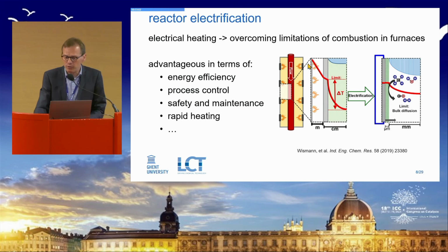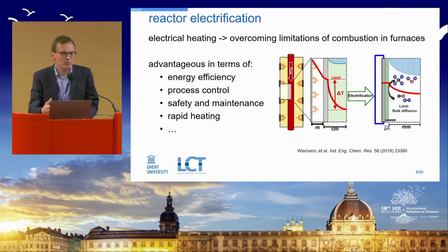And here you can see in this cartoon how, thanks to electrification, the design scale, which in the original design is situated in reactors and where the limitations occur on the scale of centimeters, changes. When making use of electricity for heating, the limiting phenomenon becomes the transfer of the reagents from the bulk to the catalyst and inside the catalyst, and vice versa.